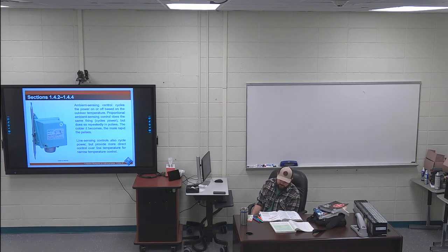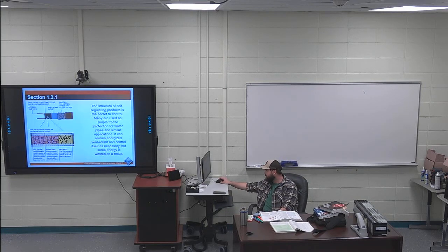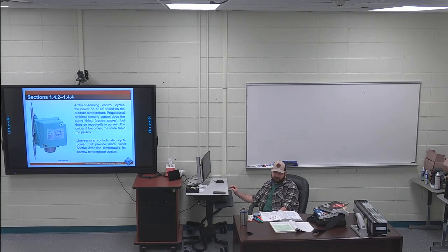141 self-regulating control, first sentence is highlighted. A self-regulating control system uses the built-in properties of the self-regulating heating cables to maintain the desired pipe temperature. That's going back to the material that's on the inside. You just put power to this and it regulates itself. It's all about the material that's on the inside. The ambient sensing control, nothing highlighted in that.